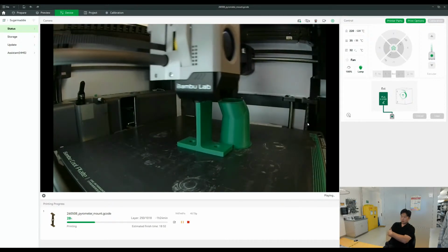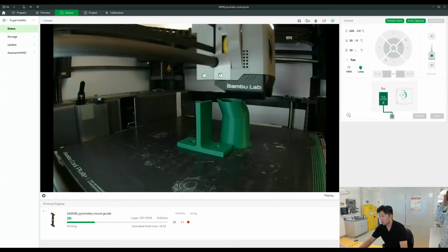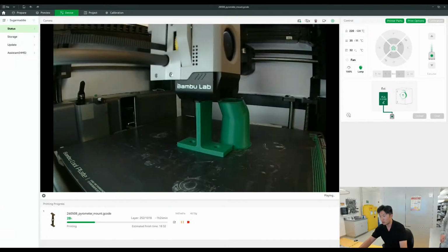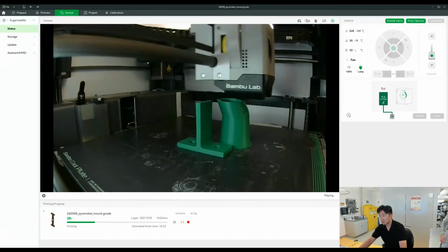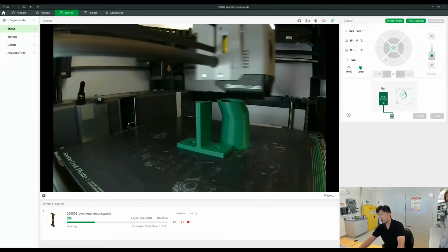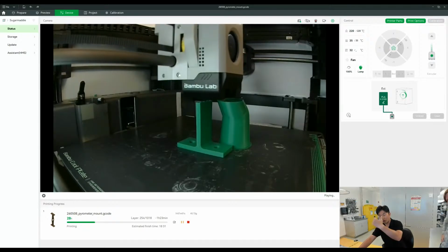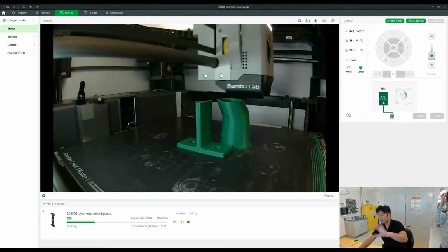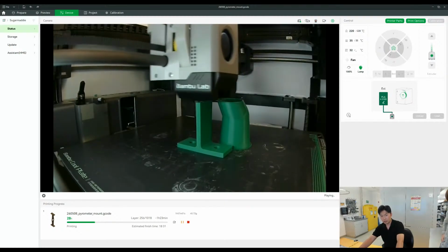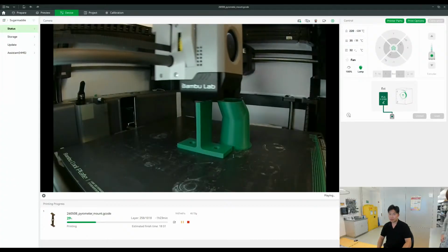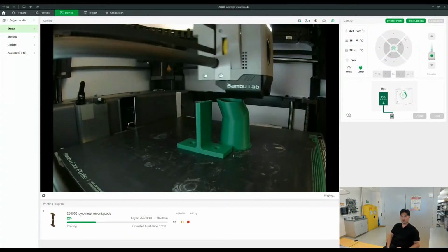Yeah. Ultimately I have my controller programmed so that if I want to, I can switch to a variable voltage control. Right now, I just set the solid state relay to be always open, and then I vary the current by clicking on the auto current. But I can just let the current be always 100%, and then make it voltage limited, and just control the voltage controller side. So it'll be essentially controlling a solid state relay. It's an option. I keep thinking this is how we should have done it from the beginning, but maybe.